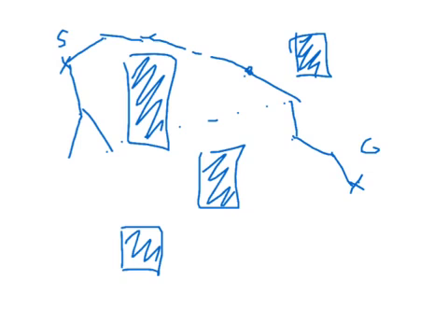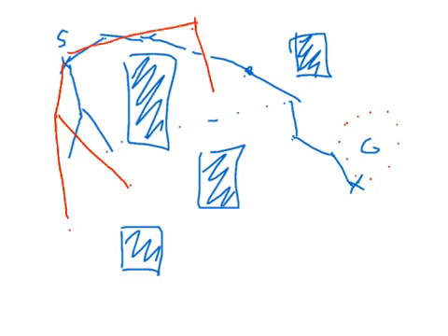Another way to speed up the search, that is finding a feasible path to the goal, is to actually pick a point close to the goal region every now and then. So let's say we put 5 points out that start from the start: 1, 2, 3, 4, 5, and then take a point at the goal. Now we can see whether we can connect the start to the goal, or the goal point to somewhere on a tree that started from the start, and we can see that we find a path like that.